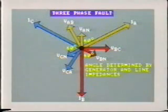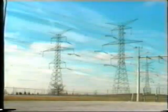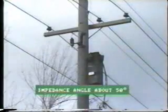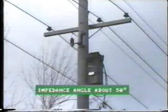Why is this? Well, this angle is determined by the nature of the system impedance to the fault. That is, the generator impedance and the line impedance. The line impedance predominates, and for a 115 kV transmission line, this is usually about 60 degrees. High voltage lines, 230 kV and up, may have impedance angles as high as 85 degrees. Conversely, low voltage distribution lines usually have a line impedance angle of about 50 degrees. Well, now let's move on to look at the conditions for a phase-to-phase fault.